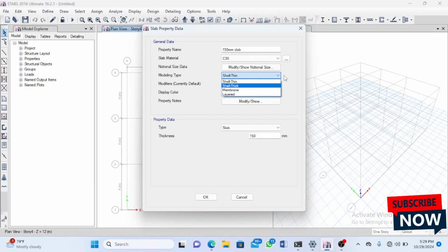And for the membrane, when you select it, it makes the slab act in a way that it does not really receive the loads coming onto the slab. So it transfers all the loads to the beam. So you can have a very thick beam when you choose your slab to be a membrane. That means the membrane doesn't really carry more loads. So all the loads are transferred to the beam. But in the actual sense, the slab is also supposed to absorb certain loads. So that's it for the shell thin, shell thick, and also membrane. So for this slab we are defining, we are going to pick the shell thin for the definition of our slab.